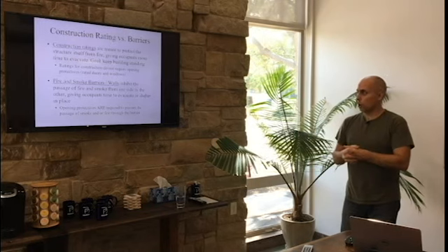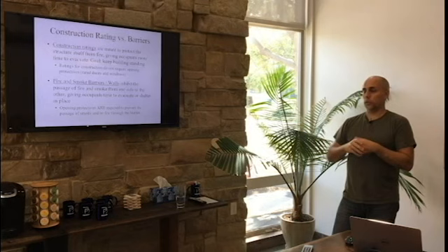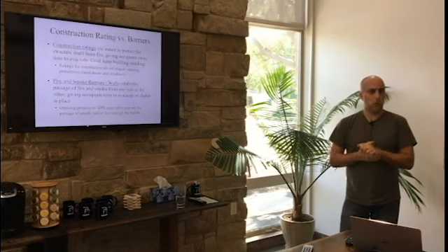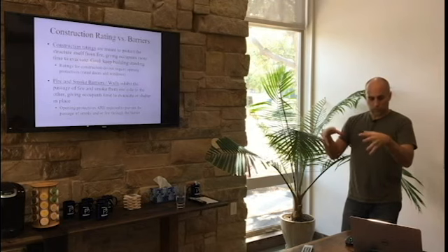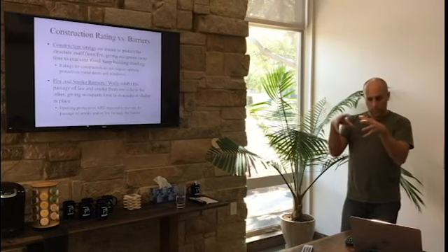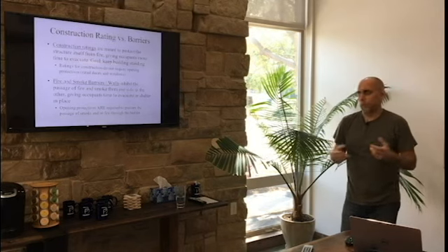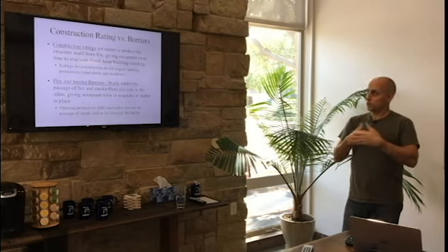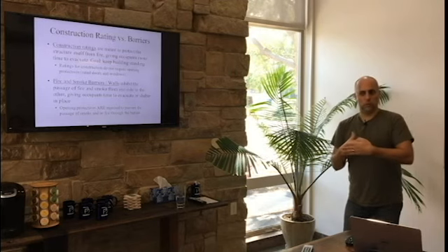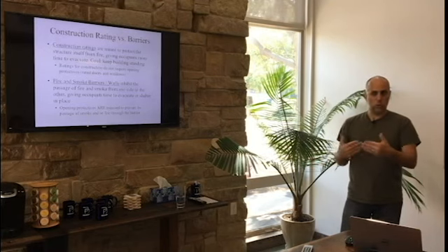Those components, those walls, and generally they're walls, but they can also be floors, because every floor in a healthcare facility is also a smoke barrier, a 1 hour rated smoke barrier. The intent is to compartmentalize, to keep the smoke and fire in a certain area to give people time to get out around it. But the two may coincide with one another. You might have a smoke barrier that is also a bearing wall, so it must stay up for 1 hour and nothing can get past it for 1 hour.